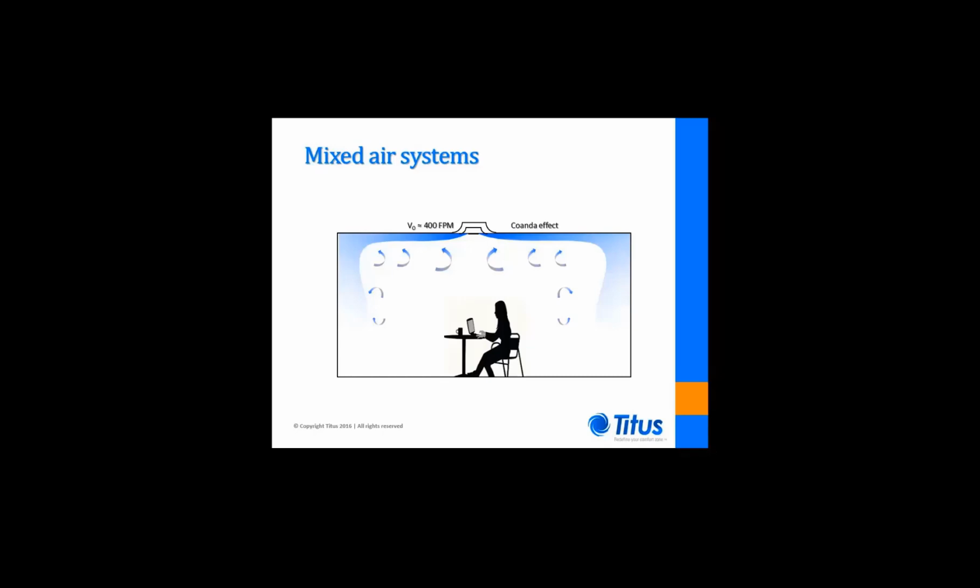Heat gains from sources located throughout the room are transferred to the occupied levels and must be included in the room's sensible cooling calculations. This includes lighting and high-level heat gains that occur along the perimeter of the space. This type of ventilation is referred to as dilution ventilation, as it uses the fresh air supply to dilute the room air, thereby reducing its contaminant level. It should be noted that over 60% of contagious disease transmission in K-12 schools is due to respiratory exchange.